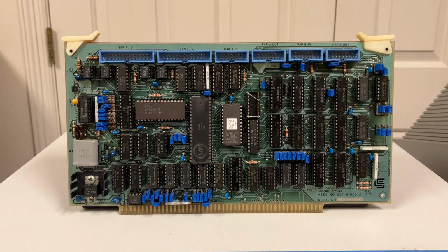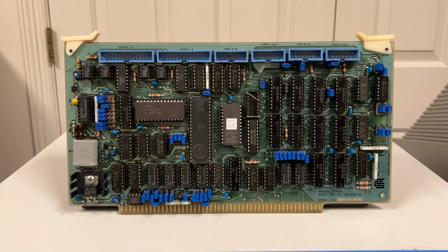For example, you could put a nice monitor on there, and you still have plenty of room to put all of Altair's ROMs on there. Those are each only 256 bytes because it was for a small 1702A EEPROM. So you could put the turnkey monitor, you could put the disk bootloader, and of course you'd want the multi-bootloader. That's the ROM that allows you to boot from paper tape or cassette without having to toggle in a bootstrap loader on the front panel. So I've got an EEPROM in here, and we're actually going to go ahead and use that in the demo